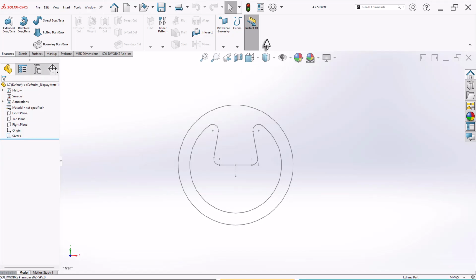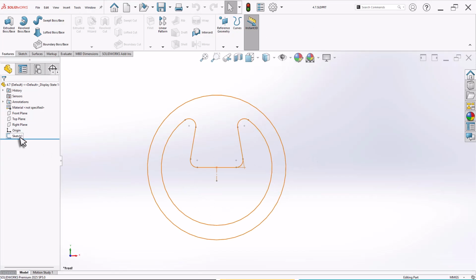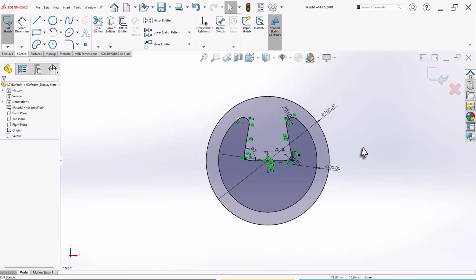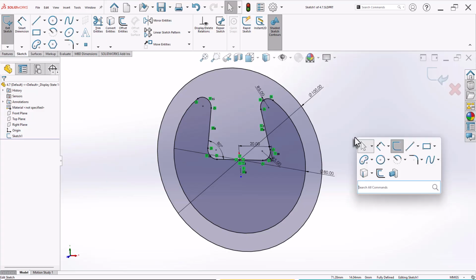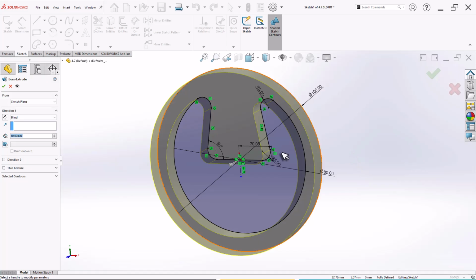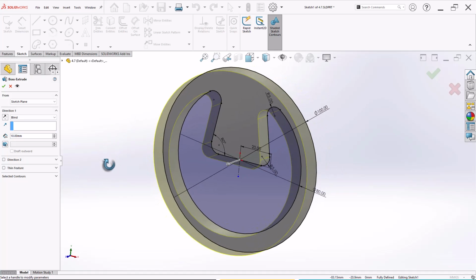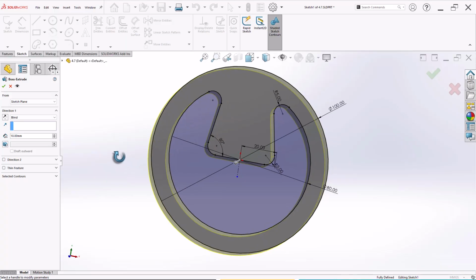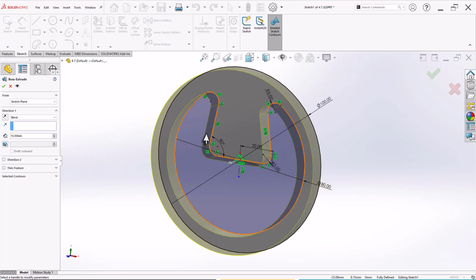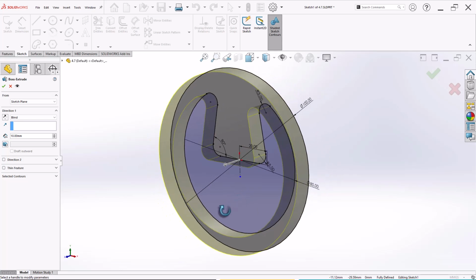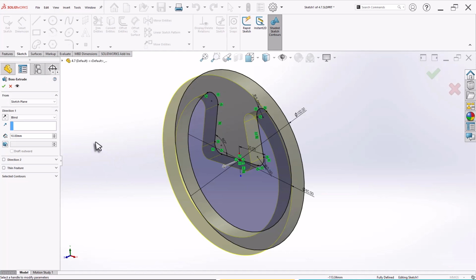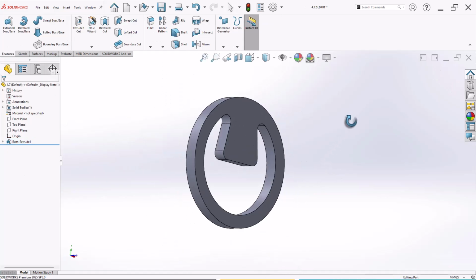Now open the part file 4.7. Now let's edit the sketch. It's very simple, you can draw it. Now let's try to extrude this. So press S, shortcut key, and choose extrude. By default, sometimes SolidWorks picks the correct region for extrusions. So this is our common region, right? Let's say it is correct and click OK. First results.